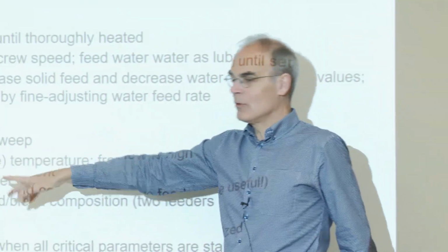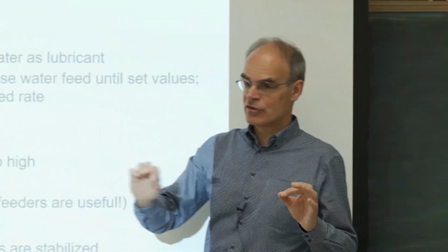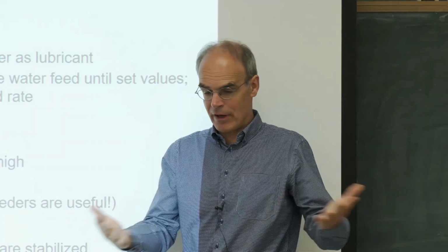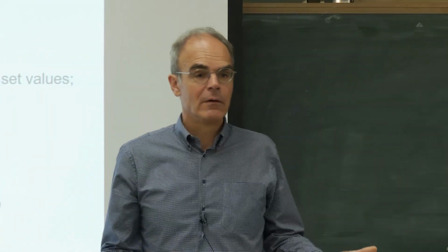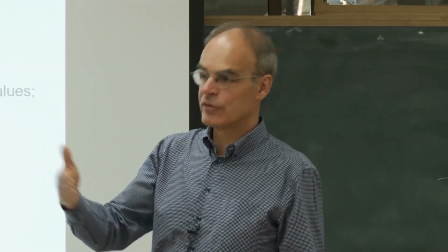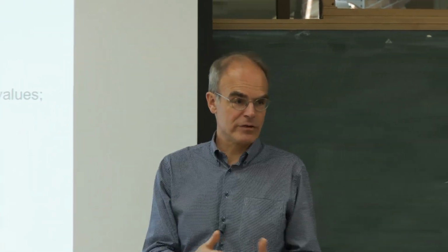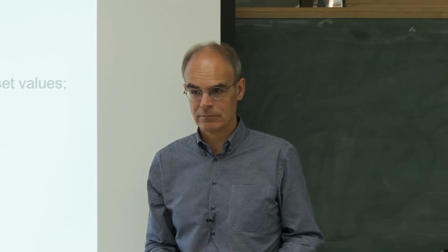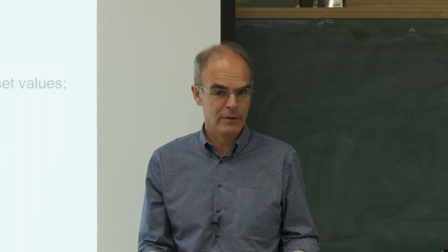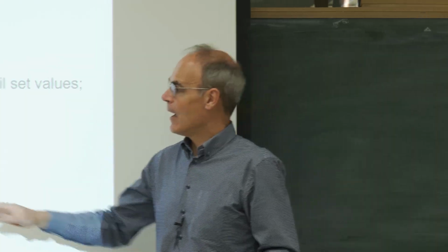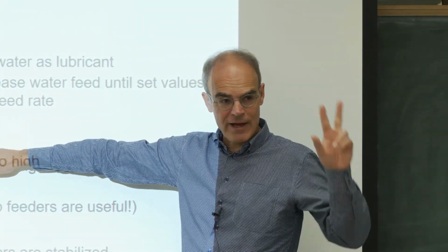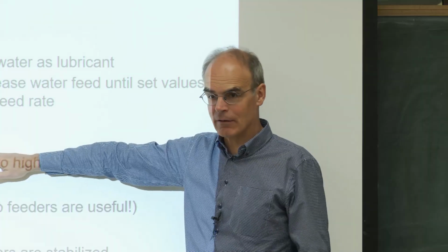The easiest to do, and it was on that previous screen, is that screw speed sweep. You have it stabilized at, let's say, a fairly reasonable screw speed, and then you can stepwise increase that or decrease that. Yeah, it's really easy. Just, I'm now at 100 RPM, let's do 200 RPM. Well, let's say 300 RPM. Really easy. It gives a lot of information, and particularly gives some information, as you see later on, on that SME parameter, the specific mechanical energy.